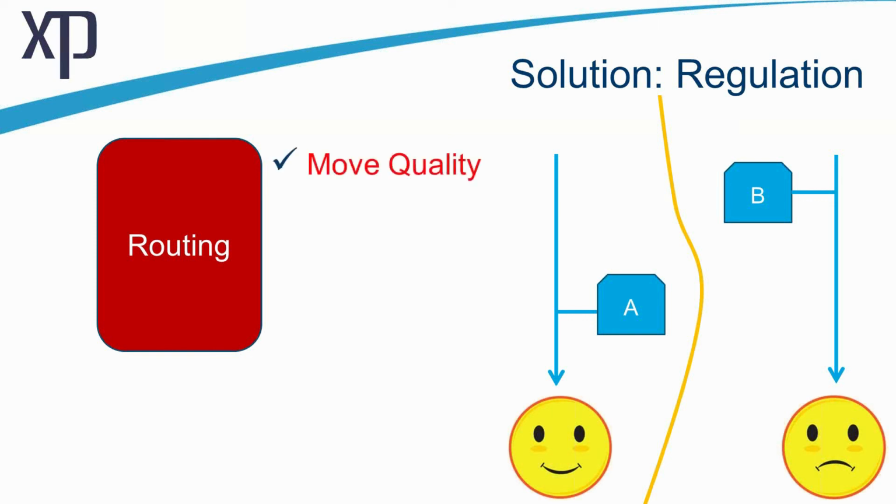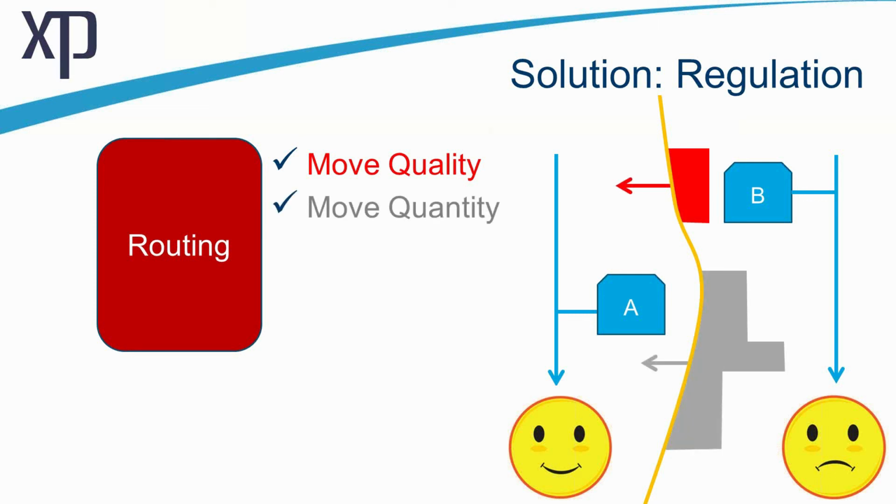So what can we do here? Well, typically we'll have industrial pretreatment, but you still may have a certain quality of flow that you might want to move. And so a model with routing and scenarios is good at telling you a certain area that might naturally drain in B, and maybe some way to drain it to A. That's less common, although it's possible. More common is the quantity. So perhaps there's a larger area or just a different area that would naturally flow to B that I can move to A. Perhaps it's 10% of the capacity.